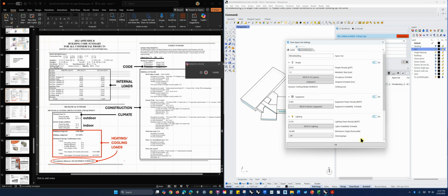If we were in an office and our desk surfaces, when the sun was out, were getting 46 foot candles or more, then we could set the dimming to turn the lights off or dim them. And that way, by dimming, we could say, well, we're getting 35 foot candles, let's just dim the lights to where we're getting 48, but we're not using as much power. So that's why that's there.